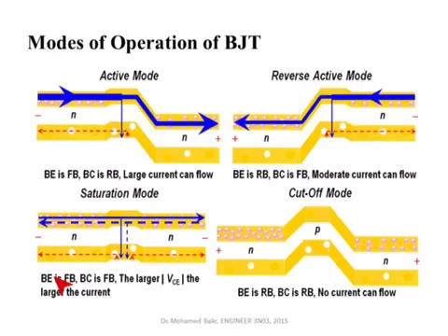This is what we call the ohmic region, or the linear region for FETs. But it's called there the saturation region. So you have to be careful. What we call the saturation region for FETs is what we call here the active mode of operation, and what we call here saturation mode for BJTs is effectively the linear mode or the ohmic mode of operation for the FETs. This one we use when we use the transistor as an on switch, when we try to make the transistor represent very little resistance, very little voltage drop. This is the mode you should be using.